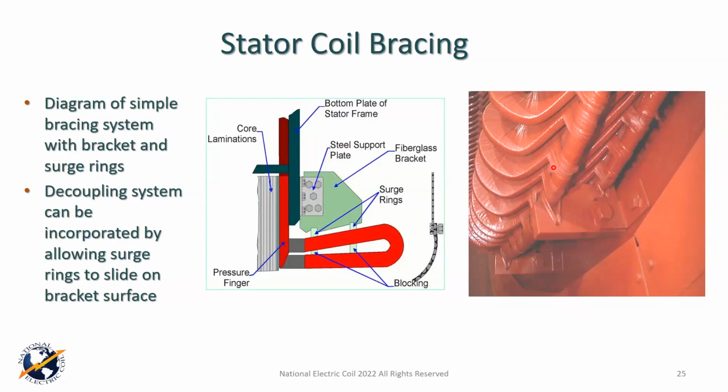And they became almost like a bowl of spaghetti because the coils became a little bit narrower and a little bit taller because of the design parameters, and you had to find a way to restrain them. But even on the older ones, you had to help hold them in place because if you have operational events or grid events or even bad lightning storms or weather circumstances, you need to hold these in place because the surges you can see in there from the electromechanical forces are pretty substantial.